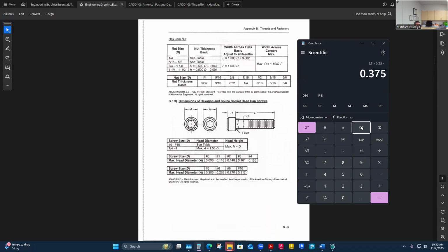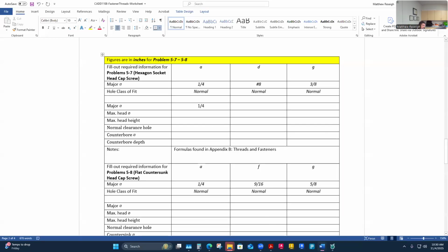So that thing has the socket head on it. That's max diameter is going to be 0.375. So back on my worksheet, that's 0.375 right here. That's critical because in order to design around that, I have to have a clearance hole bigger than that for that head to fit into, right? This is usually designed to fit into a pocket on a part. And so if I'm going to design my part, I'm going to design it so that it's bigger than this, so it fits in there. And there's a tolerance applied to that. It's kind of that clearance hole type tolerance application.